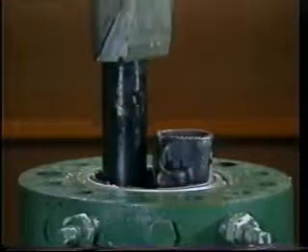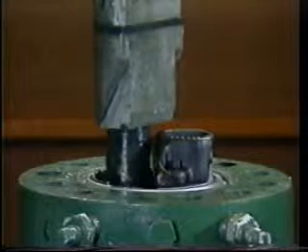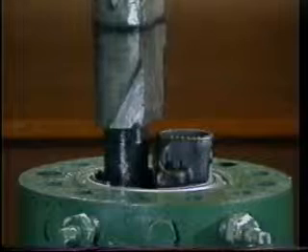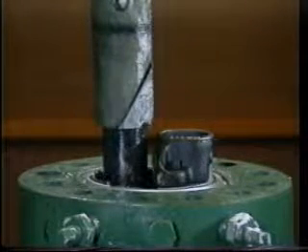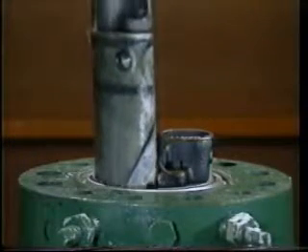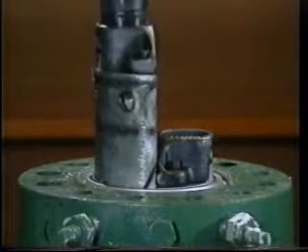At this point, let's briefly discuss multiple completion wellheads. Although as many as 5 intervals may be produced independently, multiple completions are usually limited to 2 zones, occasionally 3. A dual completion requires a dual tubing hanger of either the split type or the mandrel type. A common split-type hanger incorporates dual-segmented tubing hangers, a tubing head spool, and a dual-bore master valve.